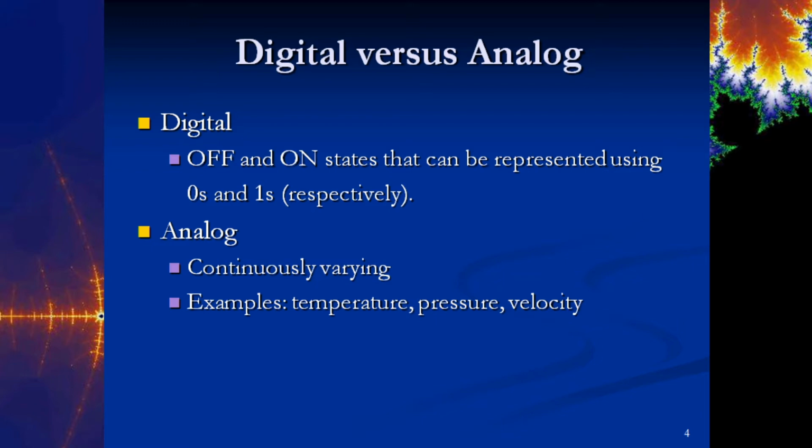So in industry, devices like transducers are used all the time to take some analog physical quantity, like temperature, pressure, velocity, whatever, and convert it into a voltage, which then can be scaled to represent a certain digital value. And so, therefore, you can have different digital values representing different points in your conversion, right, from the physical quantity into a digital quantity.